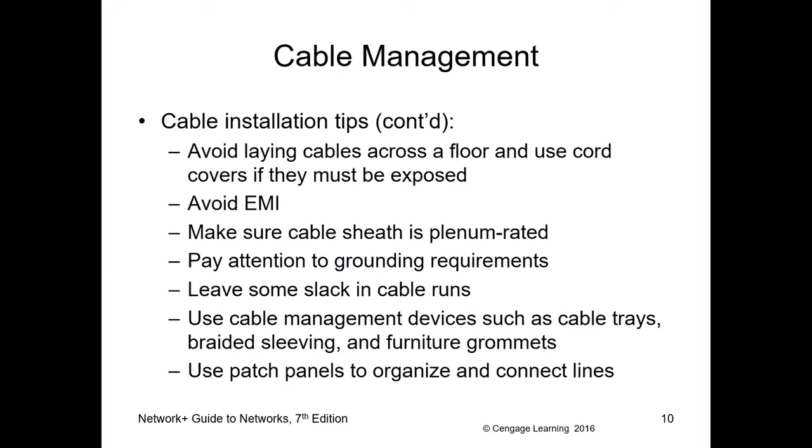Also write down these tips as well. Avoid laying cables across the floor. If you have no choice but to put them across the floor, make sure you cover them and make sure they are nice and neat. You can go through the ceilings. If you go through the ceilings, by the way, try to avoid fluorescent lights, because fluorescent lights emit enough EMI, electromagnetic interference, that will corrupt the data.